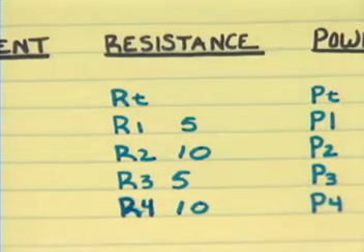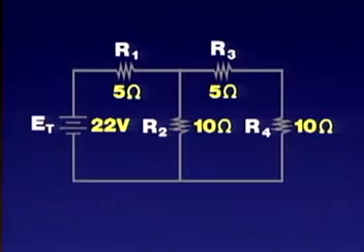You're now ready to begin determining all other values for this circuit. Returning to the schematic, the first thing you need to do is recognize which resistors are connected in series and which are connected in parallel. Being able to do this is one of the most important steps in reading schematics. Once you identify the resistors, you then can simplify the circuit. First, start with the resistors furthest from the power source, and then work back towards the power source.